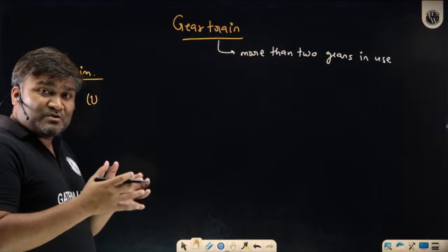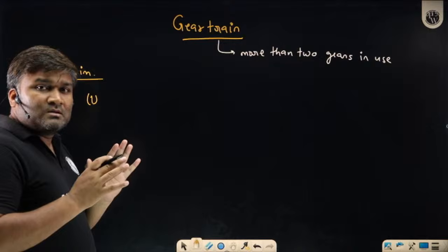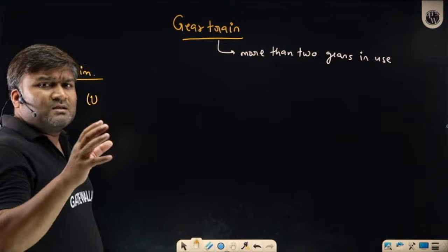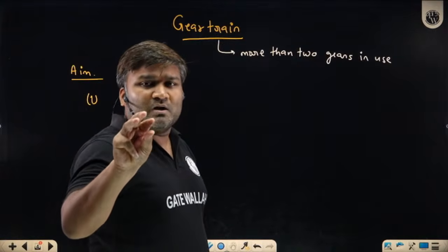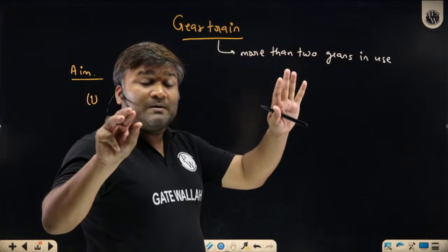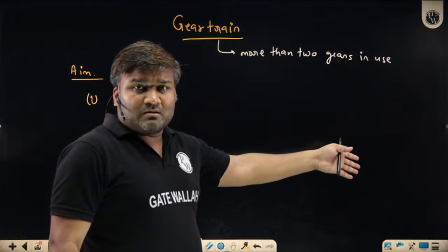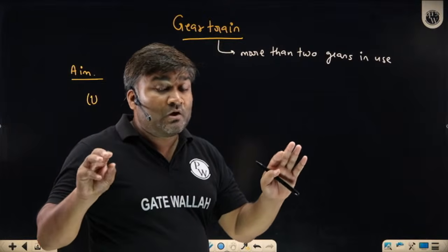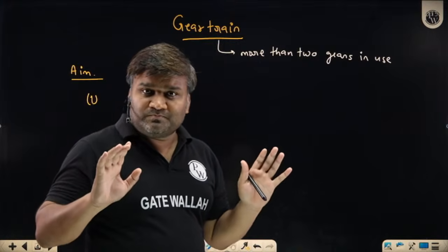To get exceptionally high velocity ratios, I must go for multiple gears. I simply cannot use two bodies. Why? Sir, if you want a 20:1 velocity ratio, that means the smaller gear is small in size and the bigger gear is 20 times bigger. Imagine, with only a 5 times size difference, you can see one is very small and the other is quite big. But if I say 20:1 or 50:1, then the differences will be unimaginable.